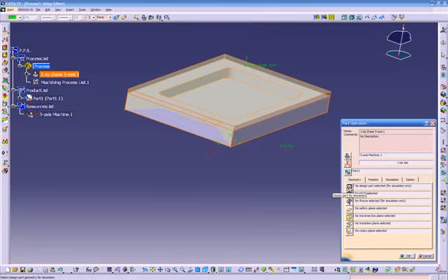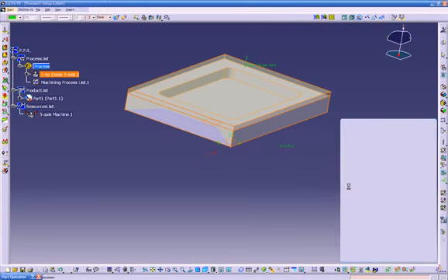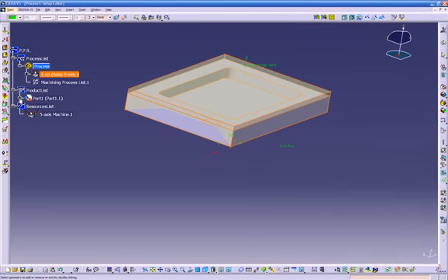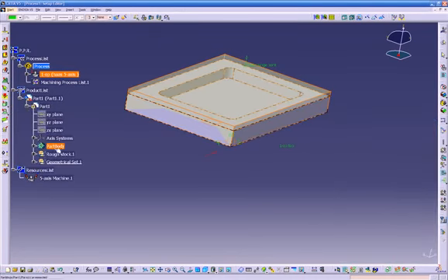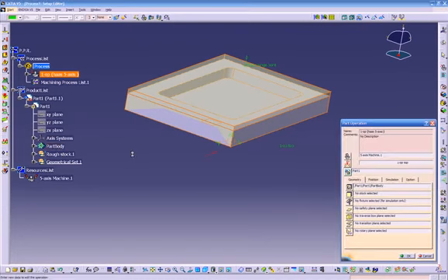Now we go to our part. We have to select our part, because the reason we do this is so we can watch the verify. So see, it says right here for simulation only. So we have to select our part, which is in here. This is our part. Just highlight it and then double click twice over here, so we get our window back.